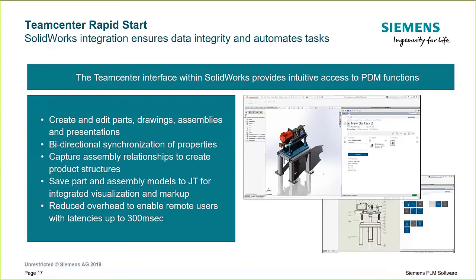To help maximize designer productivity, the integration enables designers to create, save, search, and edit objects, including drawings, parts, and assemblies. Users can selectively update in-session models to later versions or revisions without reloading their entire assembly. During the design process, the Teamcenter environment tracks and manages the creation of new product revisions or version updates for work in progress. As a result, designers spend less time finding the correct revisions of SolidWorks data.